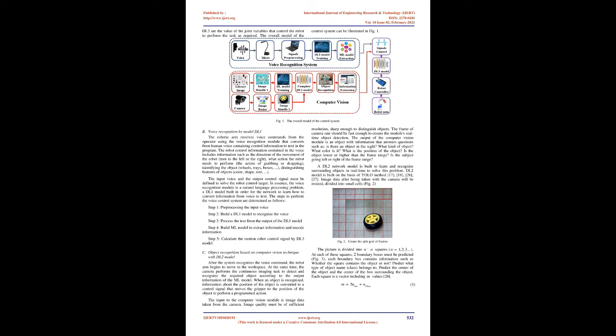based on computer vision technique using Deep Learning Model 1. Deep Learning Model 2 is used to solve the inverse kinematics problem, with the input being the position of the identified object in the workspace and the output being the value of the corresponding joint variables. The joint variable values are converted to control signals for the drive motors, ensuring the robot performs motion and object pickup. DL1, DL2 models are built and tested in Python language with support libraries. The 6DoF robot model is practically fabricated to experiment with object recognition and grasp problems.